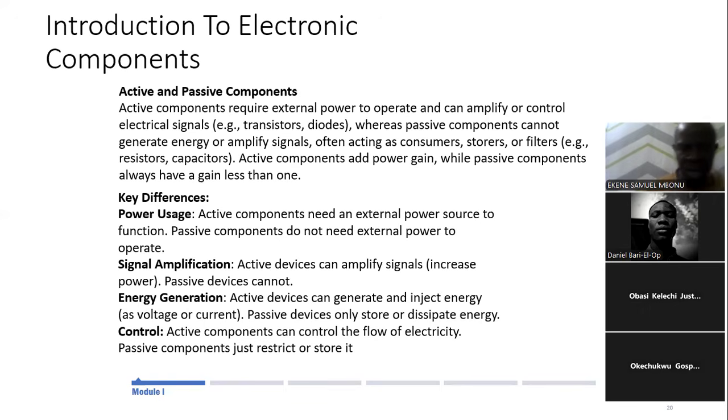If you connect everything around the IC and you don't power it, you are just wasting your time. Or if you use an operational amplifier and you don't power it, it's not going to work. Your circuit can be correct, but without power, it won't work. But stuff like resistors and capacitors, you don't need to power them. Just connect them. When the circuit comes on, it begins to work.